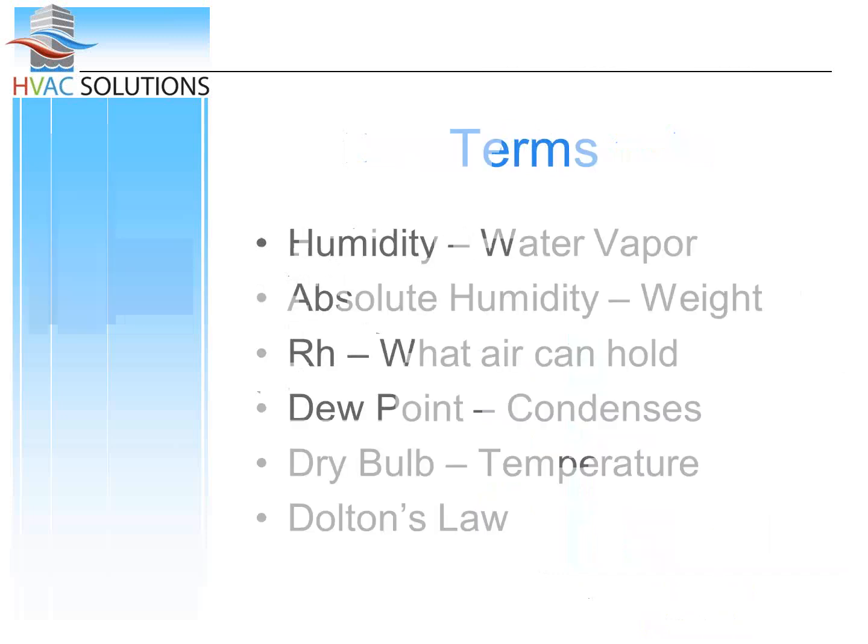You take a house that's got a huge fireplace, it might not get to the other side. So the law is always in effect. It doesn't always work out if there's something that is combating that law. So you can hang your hat on the law, it's in effect, but just because it's 35% relative humidity on one side does not mean it's 35% relative humidity on the other side.